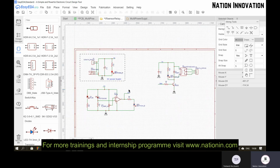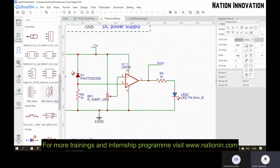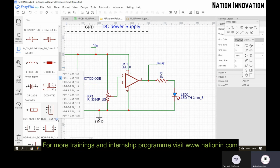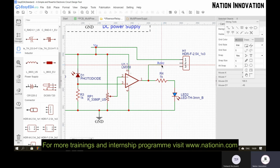So if you want to get these three terminals at the same time, you can connect a header. So the header is here. I need a 1x3 header, and I can connect this V in to my first pin, and you can connect an output here, and you can connect a ground pin here. So you need not search for the inputs, you can get them directly here.